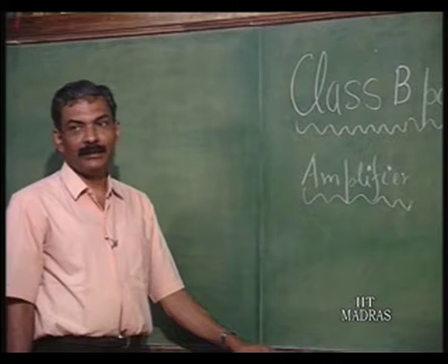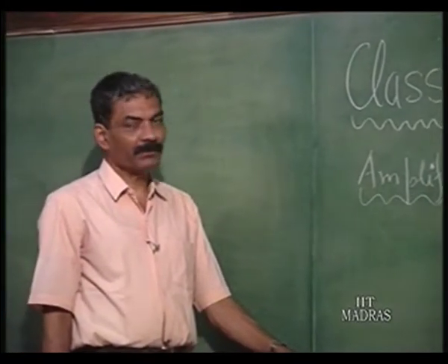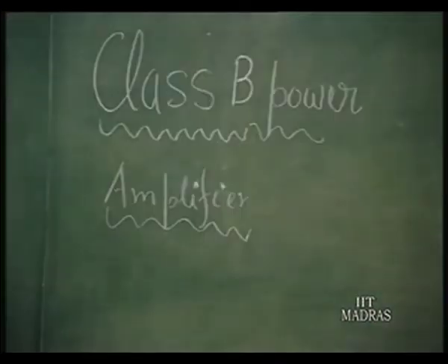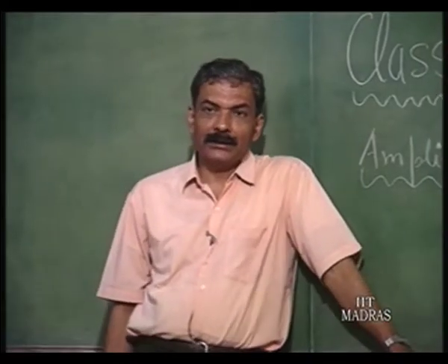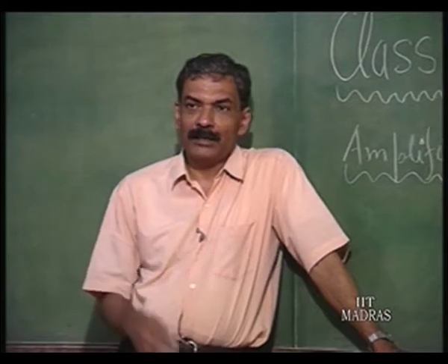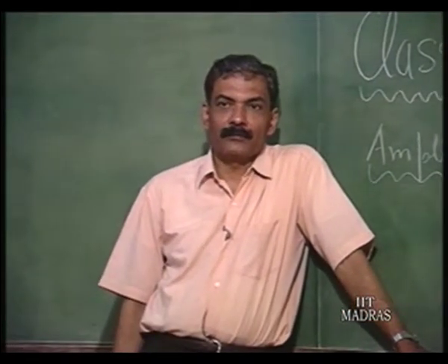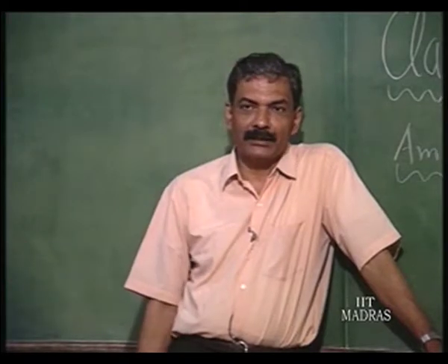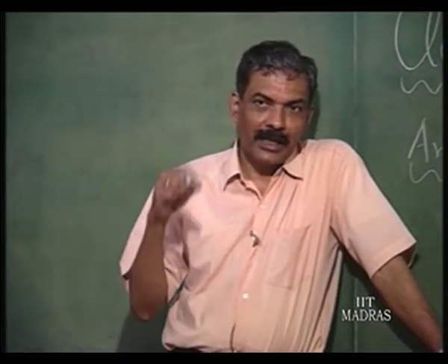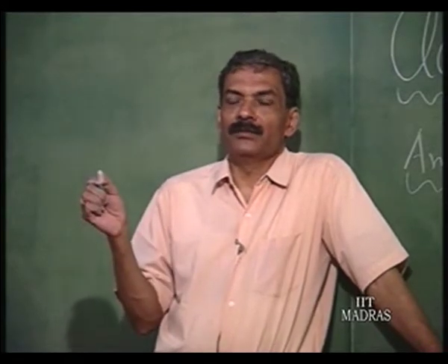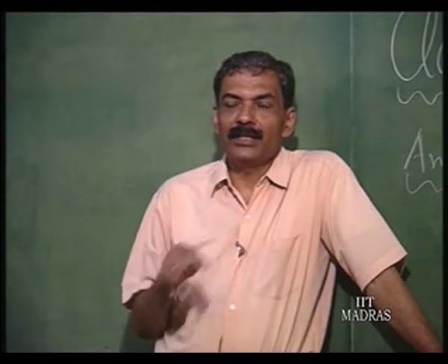This is covering 90% of the classical power amplifiers available to us. So, this is class B power amplifier. What we have discussed is class A power amplifier. What is class A? Class A says that if you have a transistor operating at 1 milliampere quiescent current, the current can change from 0 milliampere to 2 milliamperes, that is all. If you have it operating at 2 milliamperes, it will change from 0 to 4 milliamperes on the other side. So, this tells us that the transistor has to keep waiting with a constant quiescent current, and keep dissipating a lot of power before it encounters the signal. This is not a very efficient way of doing it.